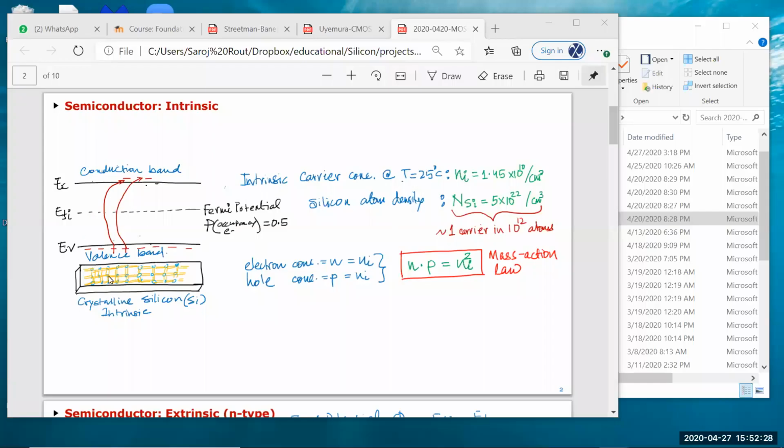All right. So band diagrams, like I said, has two aspects to it. What you see, these lines over here, they are the potential energy of electrons, which are called energy states of a particular configuration of a material. What I mean by particular configuration of a material is, for example, here I've taken a crystalline silicon material, right? If I just take a single isolated silicon atom, this whole band diagram will look different.